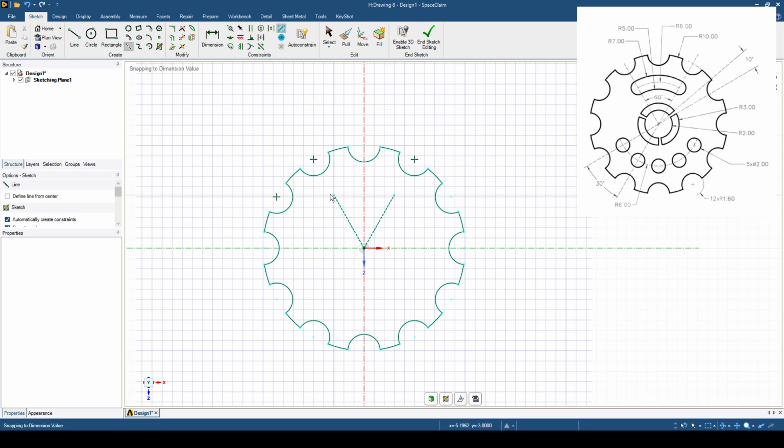Now I'm going to draw these two small circles there. They are circles where the inner radius is 5 and the outer radius is 7. That means these circles have a diameter of 2 mm. So I'm going to draw the 2 mm circle and the other 2 mm circle. After that we go to the 3-point arc, choose 1 point there, 1 point there, and draw.